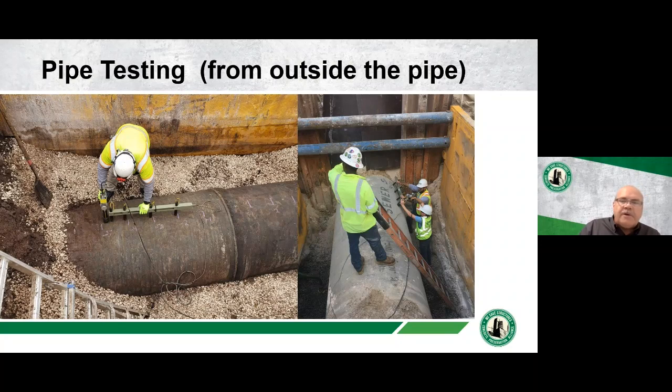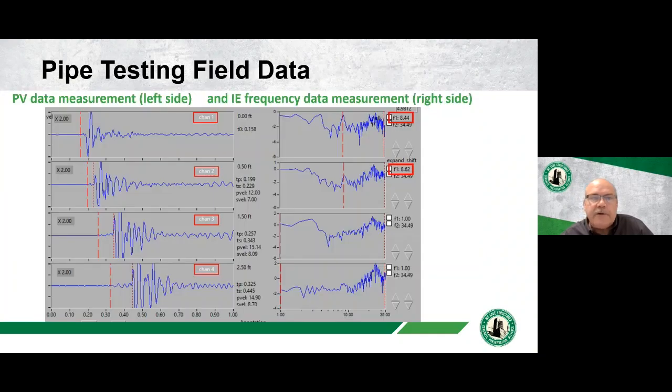If we can open up a 20 or 30 foot section of pipe, we may be able to have access to maybe up to 3 joints, 2 full sections of pipe, and we can strategically pick these excavations along the system. And maybe we can get some information on 5 or maybe even 10% of the system. Based on the information we have, we can glean the integrity of the overall system and understand if it's more or less than what it was designed for.